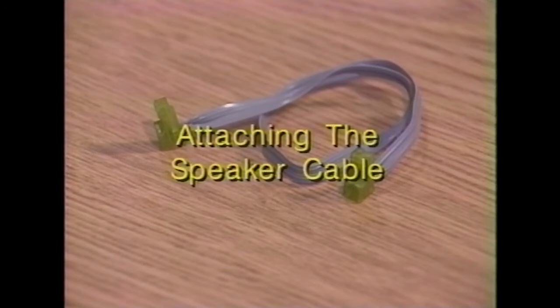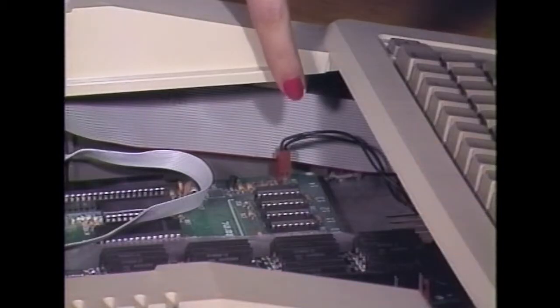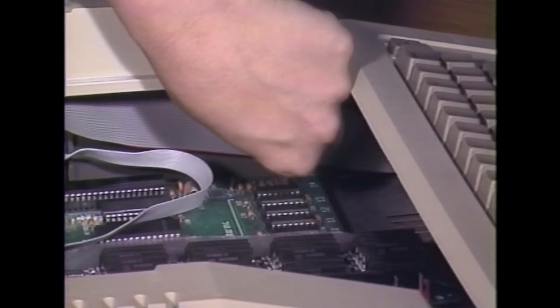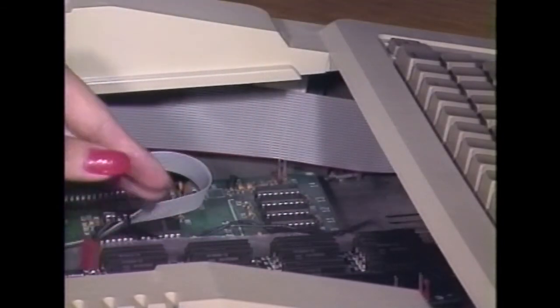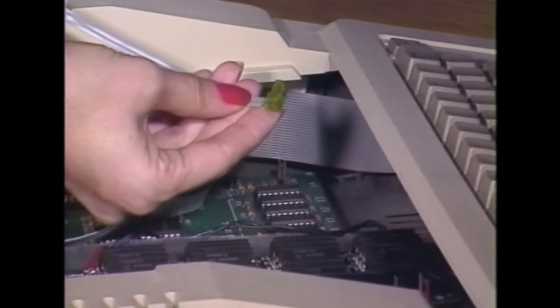Attaching the speaker cable. Have the supplied speaker cable ready. It has a 2-pin connector on either end. Disconnect the existing Molex connector from location J18 on the Apple's motherboard. This connector is located on the right corner of the motherboard closest to the keypad.